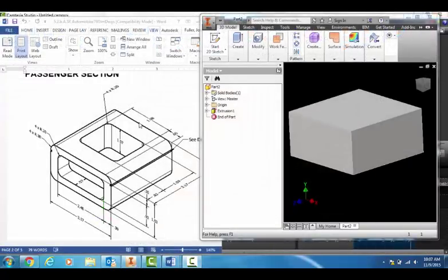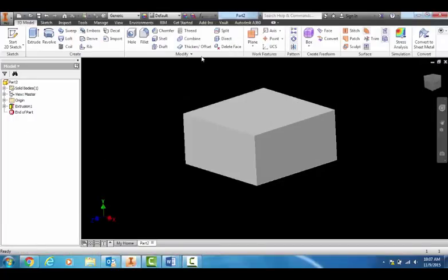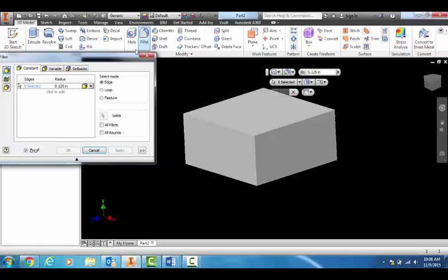All right, once again, let's come back to our assignment over here. So we have these curved edges here. Notice there's four of them, with a radius of 0.3, on this outer curve here. So let's come back to our Automoblox body assignment here. Let's click on the fillet tool right here, and let's make a radius of what it said, 0.3.